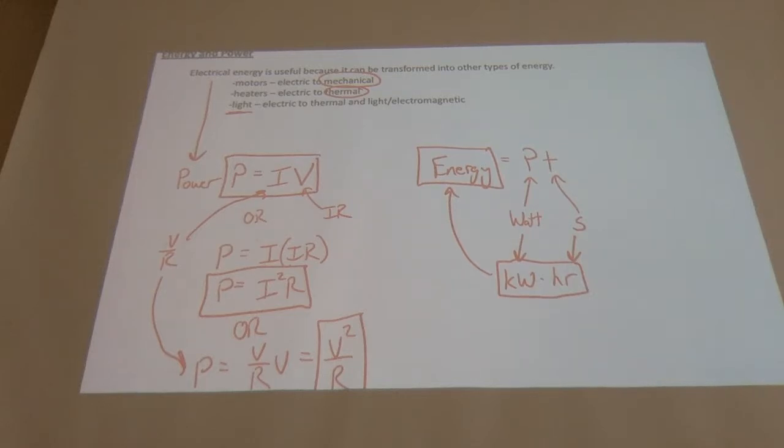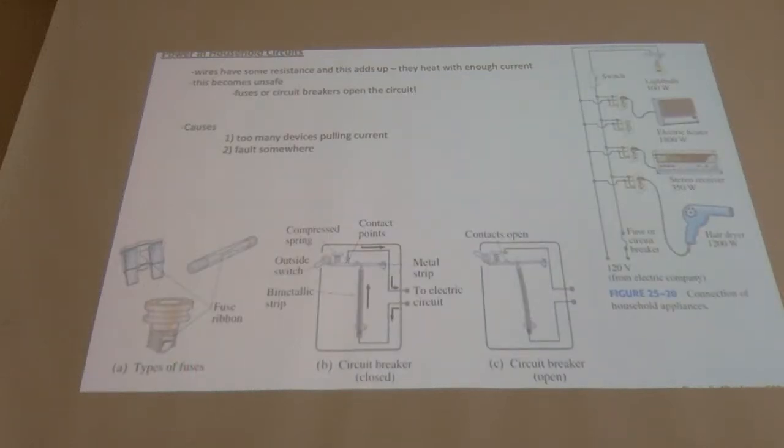So how does that work in your house? We're not going to talk so much about how it works, but more about how it fails, just to keep you all just a smidge safer, okay? So we know that wires, like copper, don't have a lot of resistance, but even in copper, there are free electrons and all these nuclei that they keep colliding into. So there's still some resistance. If I take a house or a large building like this and have many meters of wire, all that little bit of resistance starts to add up, okay?